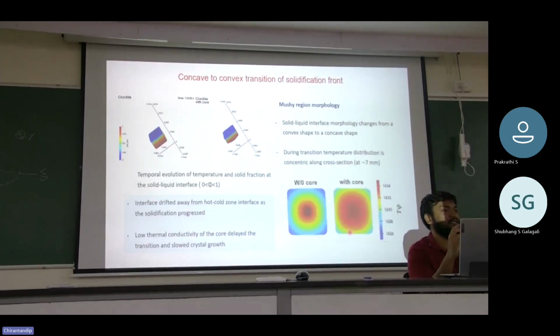Visible. So you can see its topology changes as the simulation goes on. And from this we can also come to know the thermal gradients, which we can map using this, and that is very important for the microstructural properties of the alloy that is getting solidified.